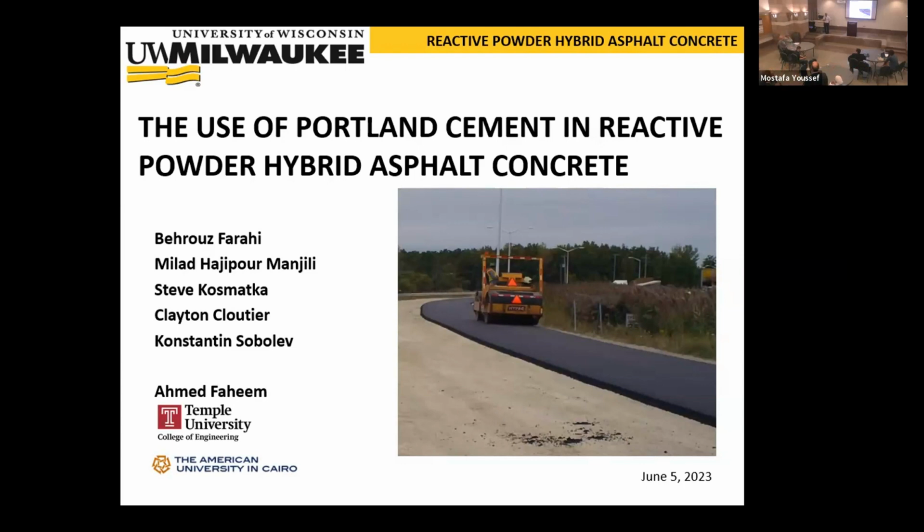What they actually suggested is that they have an injection system somewhere in the middle of the drum. So when coating is already achieved, the powder is injected in the middle and incorporated inside the already formed asphalt. In this way it's not clogged, and it's not covering the aggregates. This was tried and it was very successful, because companies already have systems to inject, for example, cement kiln dust, which was used in the past also for anti-stripping. But now cement kiln dust is not there anymore for some reason, so they had systems where we can inject cement or fly ash.